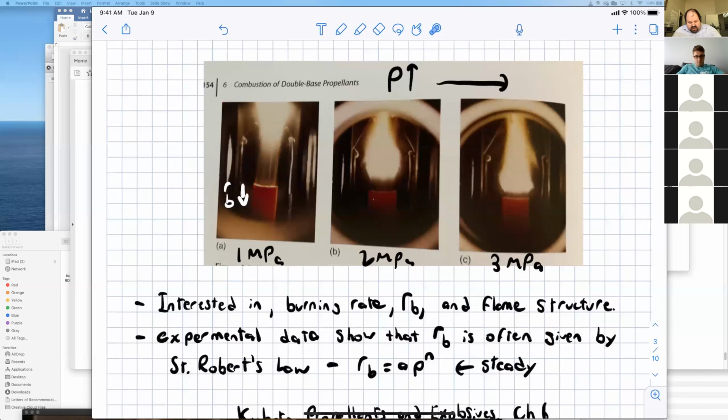We are interested in the effect of pressure, because for a rocket, you can control the pressure via the size of the rocket nozzle. Obviously you want to make the pressure as high as possible, but also make it safe for your system, and make sure that the propellant doesn't do anything too wild. So we need to understand how the propellant burns as a function of pressure.